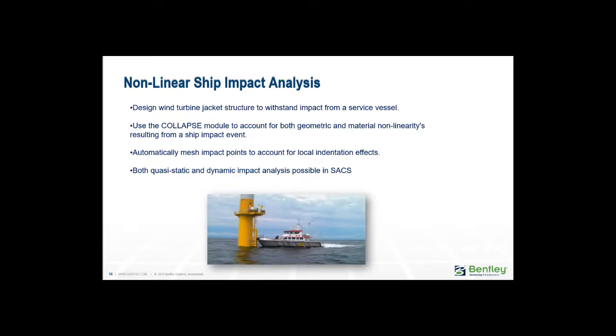The nonlinear ship impact analysis can be conducted using the SACS collapse module, which can account for both geometric and material nonlinearities resulting from a ship impact event. We can automatically mesh the impact points to account for local indentation effects, and both quasi-static and dynamic impact analysis are possible in SACS.